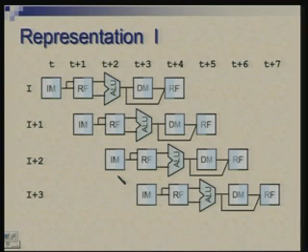Another situation which can lead to structural hazard is if your ALU has to do very complex operations which inherently take multiple cycles. So far we have been talking of add, subtract, compare and so on, but suppose we were to extend our design to include multiply and divide. All right, we have discussed designs which are single cycle design as well as multiple cycle designs. Particularly for divider, it's possible to have a faster divider, but let us say we know only how to divide in multiple cycles. Okay.